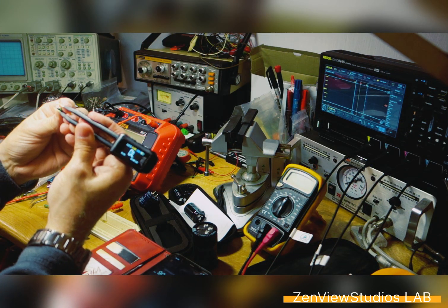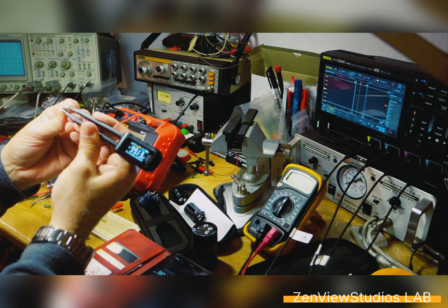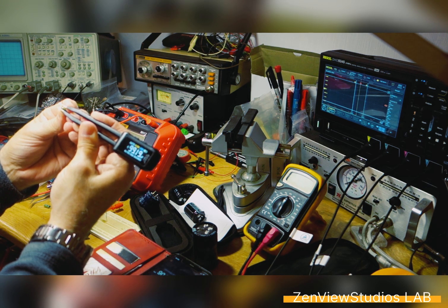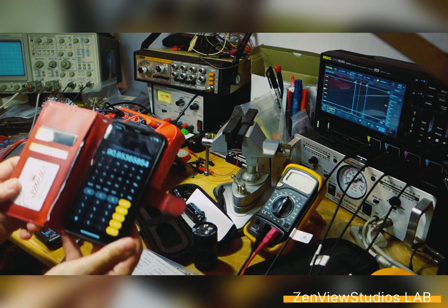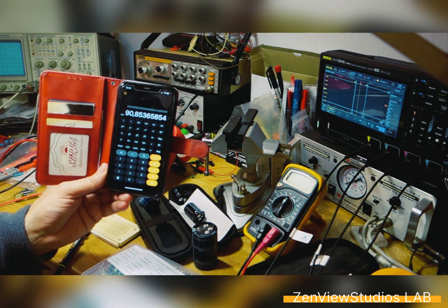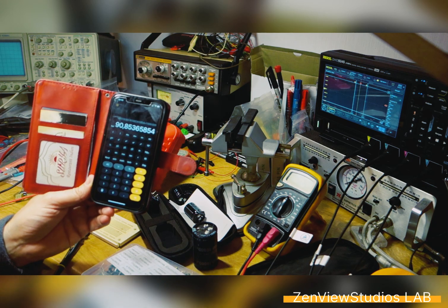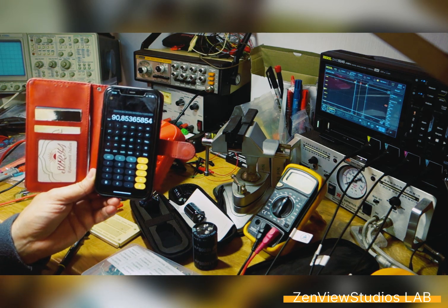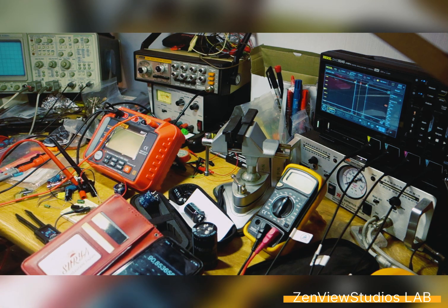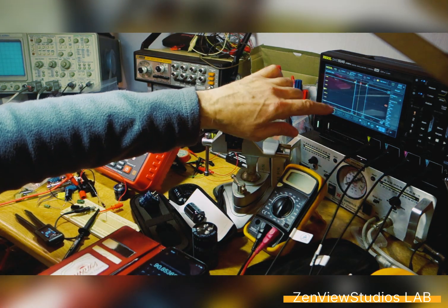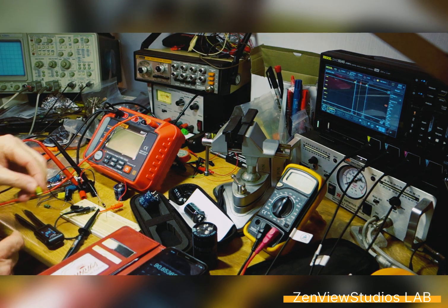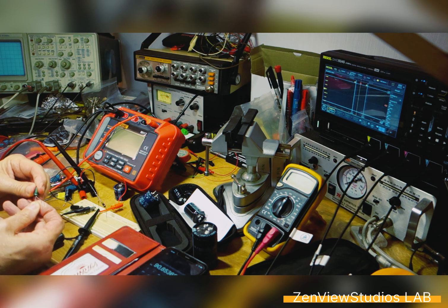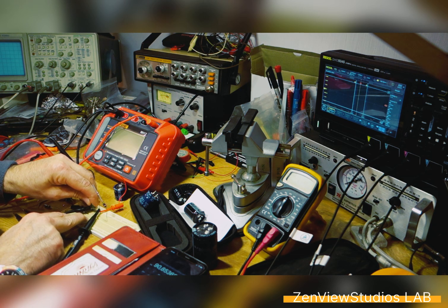So I took off the capacitor. Here is what the meter reads, 99.19 microfarad at 100 Hertz. Okay, and the calculation gave 90.85 microfarad. So obviously the precision is not as good here. This is the instrument that's lacking precision, but you get the feel that it's okay since it's quite in the range. I can put it back in there.